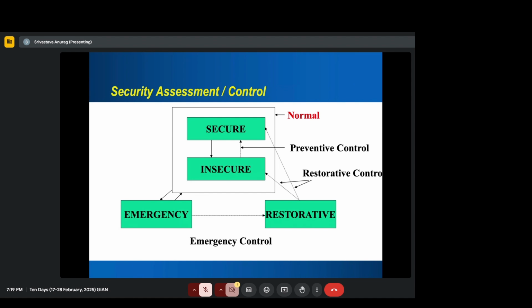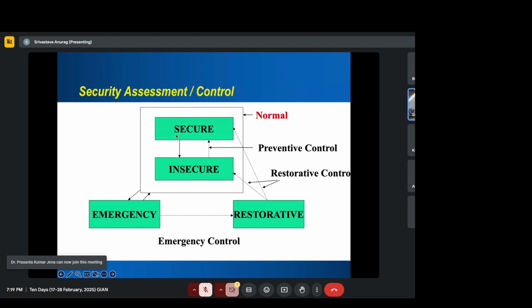One line and two line, which is a double circuit line, is both out. So we make a list of those, and then we decide that if all of that list has gone through and run the power flow without violating any constraint and without violating any load constraint and limit constraint, then we call it secure.